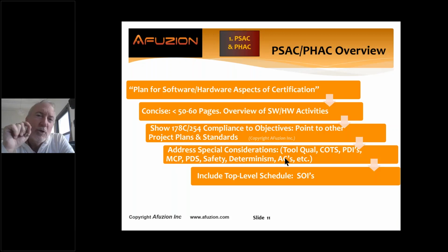No, you all define in your PSCP, your project-specific certification plan, your cert basis, the basic rules that apply to your approval process, how you're going to show airworthiness, which ACs, advisory circulars, apply. And we want to include a brief top-level schedule. When are your SOIs? When is the certification authority, EASA, military, CASA, Transport Canada, FAA, expected to be involved with them?